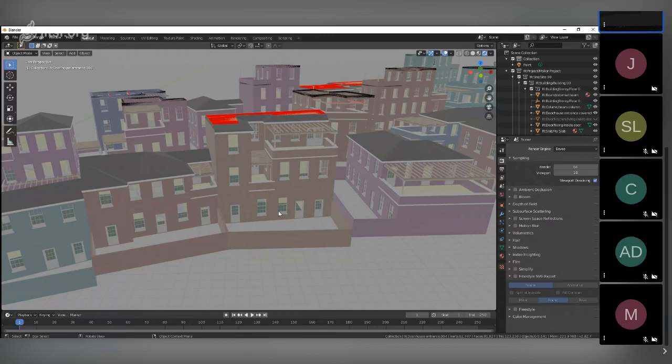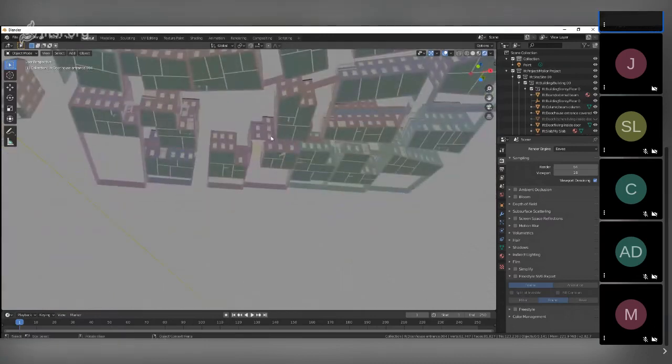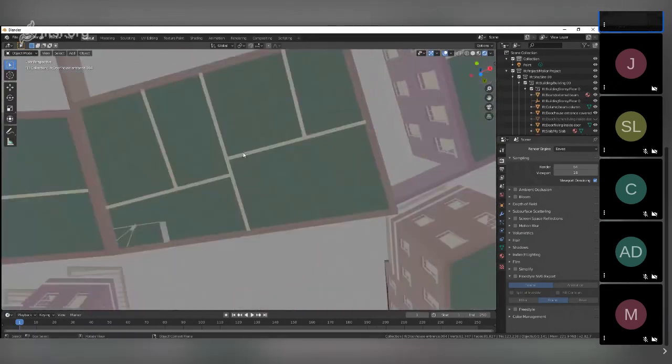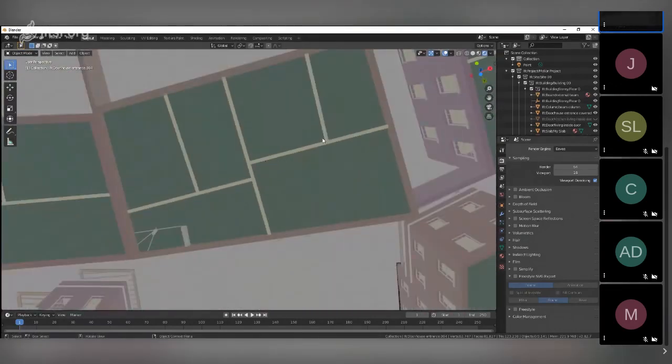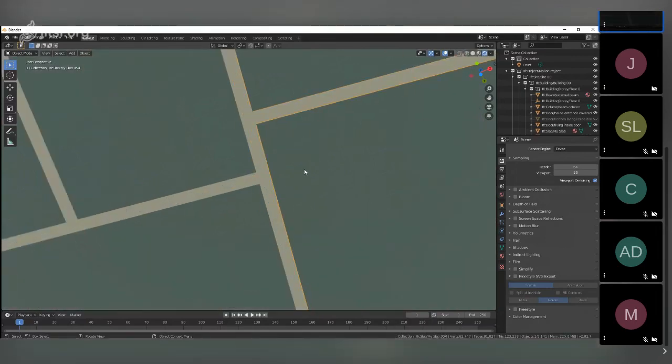If you look at the corners of these buildings, all the junctions between walls are generally T sections. They don't have to be, but they are. So if you see these walls here, it's a T section junction. Whereas with post and beam, that's actually quite awkward, because you would need to have two columns quite close together to support these walls here, or this corner.